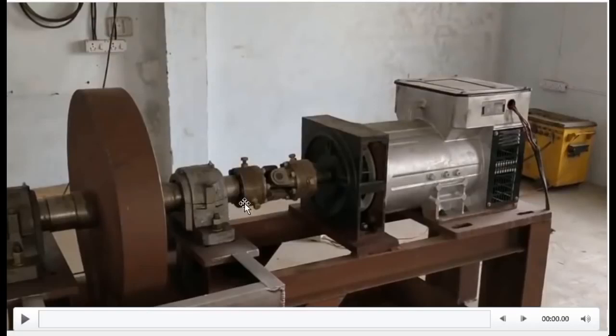You can also use steel irons that link the flywheel to the generator, and you also have your bearings here. Sometimes if you don't have money to buy many bearings, you can just link the rods directly from this place to this place using one bearing. One bearing is okay. Or if it's a shorter generator, if it is not long, you can just link this to the motor and to the generator without the bearings, just to cut down the cost.